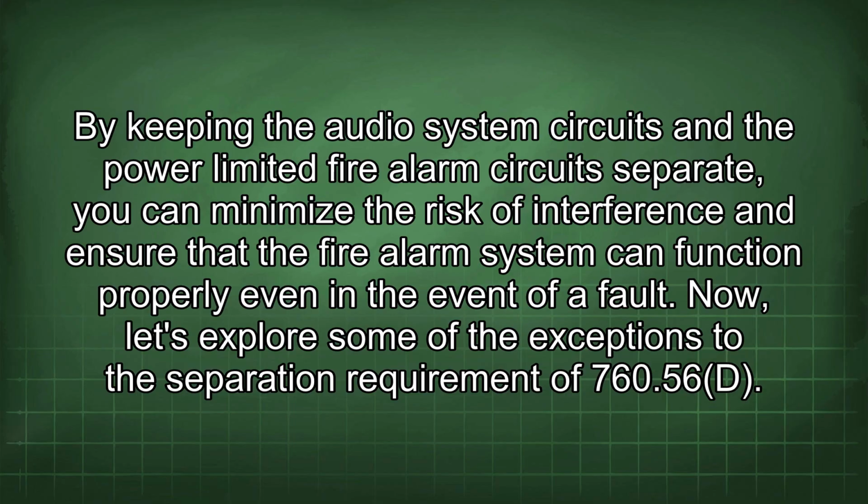By keeping the audio system circuits and the power-limited fire alarm circuits separate, you can minimize the risk of interference and ensure that the fire alarm system can function properly even in the event of a fault.